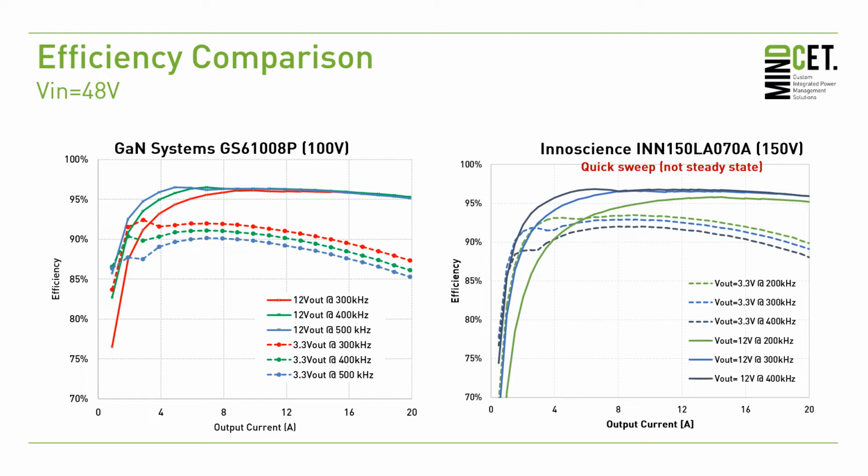And again, the larger physical package area or size of the GaN Systems devices will allow to dissipate more power, or for the same dissipation as the InnoScience device, run a bit cooler, whereas the InnoScience device has a slightly higher efficiency. These two parameters need to be traded off against each other, and it will really depend on your application to see which one is the more suited.